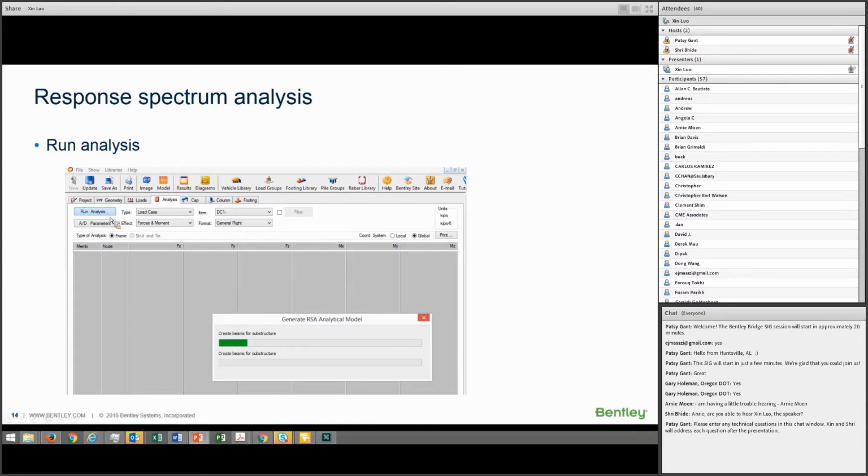What happens now is the mass table together with that graded model and the design response spectrum are sent to the stat solver to generate the response spectral analysis results for the whole bridge. In the meantime, the other load types, such as dead loads, live loads, wind loads, defined by you, are also sent to LBC Concrete its own solver to generate the analysis results for the substructure. You can see here.